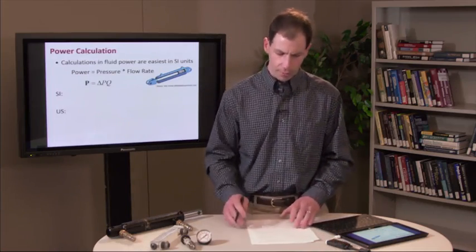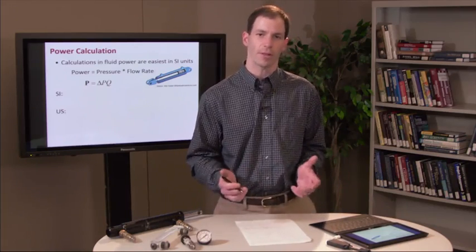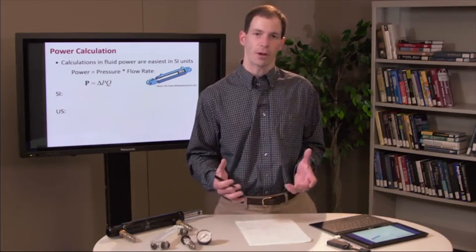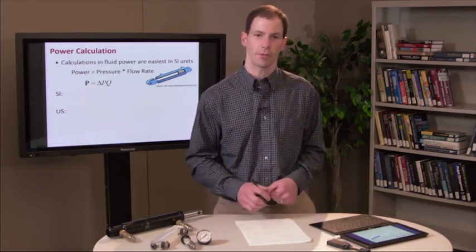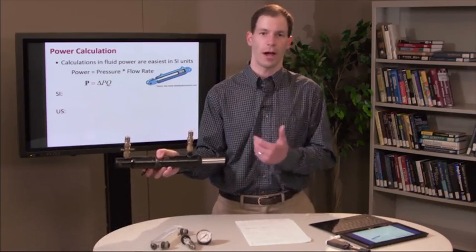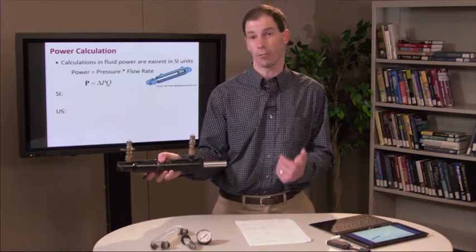So, some power calculations. I was mentioning that I recommend doing your calculations in the SI system. Let me illustrate that now. Power in hydraulics is simply the pressure drop times the flow rate. So maybe I've got a hydraulic power going into my actuator. I've got to know what the pressure drop is, so I need a reference pressure.